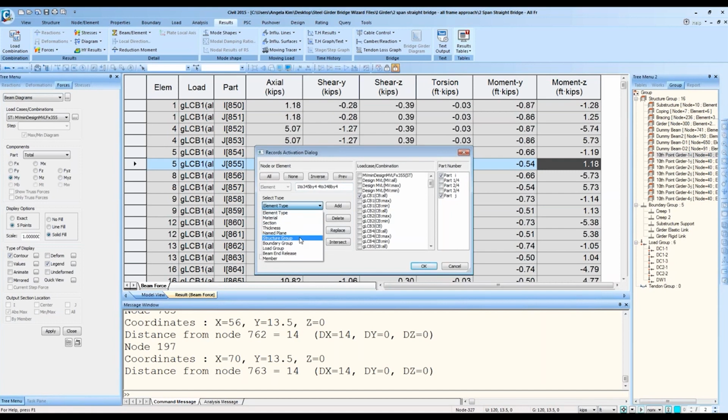So 10th point locations can be found in the structure group. Going down, you're going to see different groups: substructure, capping, meaning the pier cap, bracings, girder, and then the dummy beams, the transverse dummy beams, and then we have the 10th point girder groups showing up. And these, let me try 10th point girder 1I. And remember, it was the I node of the group of elements, right?